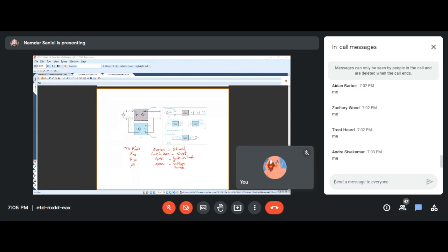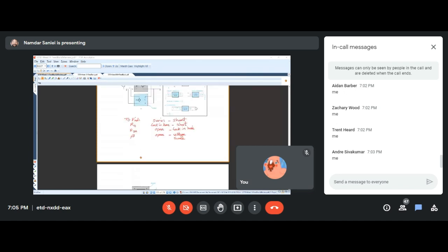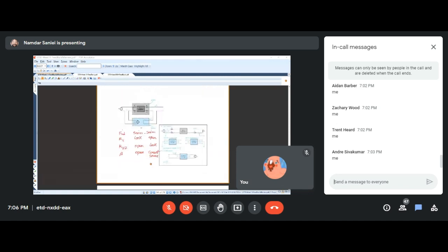But just for the gain, on the output side, shunt is translated into voltage source. So we either have a voltage source or a current source out here. But remembering shunt means voltage source, then we know that it is this voltage over this voltage as the gain that we need to find. So there's nothing that you need to know about the two-port networks using this technique. And it basically helps you in finding R11, R22, and the gain for all these cases, for each case.